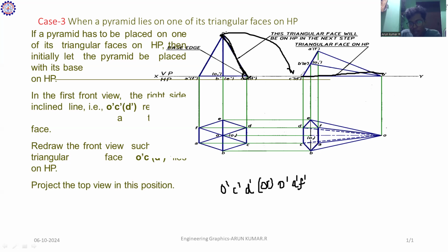You point it on C and cut the arc likewise. Similarly here, this is the side. Either taking this side or this side, both are the same value. Measure the distance with the compass, and placing the compass on O, cut the opposite arc. The two arcs meet at one point. That side is called A dash F dash. What is the remaining one? I have to mark B dash and E dash.